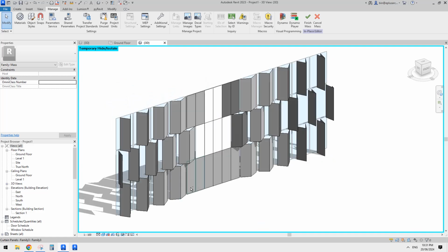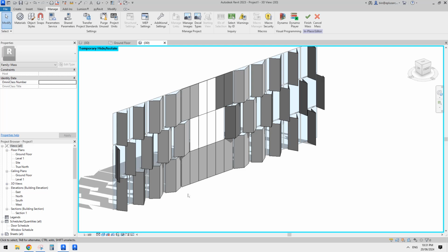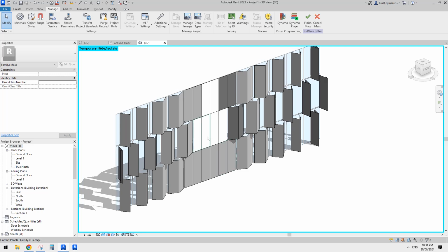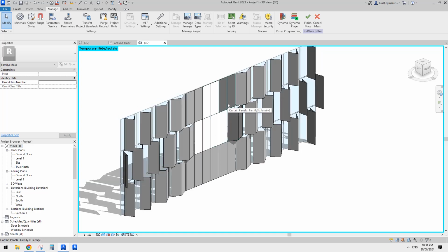Also sometimes it can be helpful that on Shaded, the color changes depending on the lighting setting. When you change the lighting, or choose a different time of the day, they will all look different. So if you really want to make sure the material you use is the right one, you can use Consistent Colors.